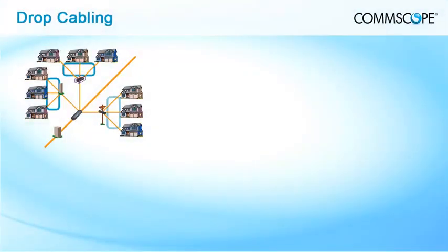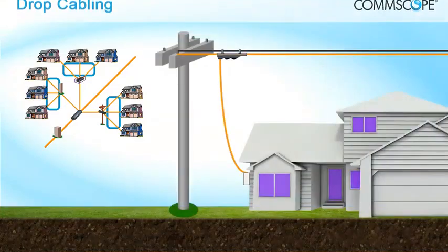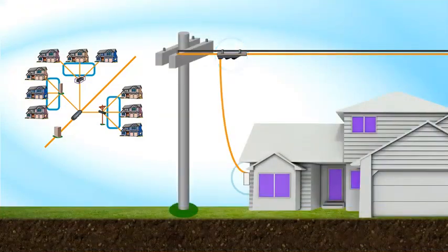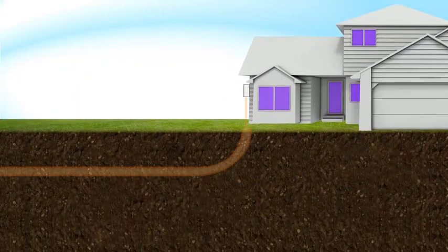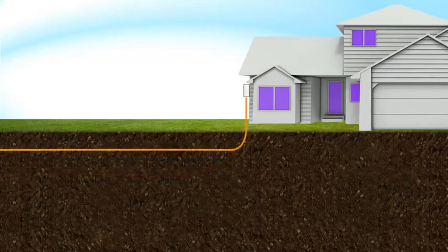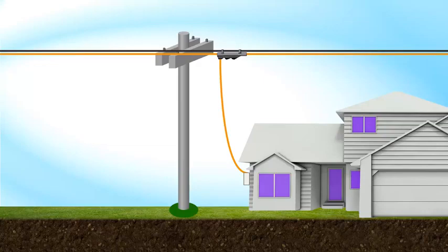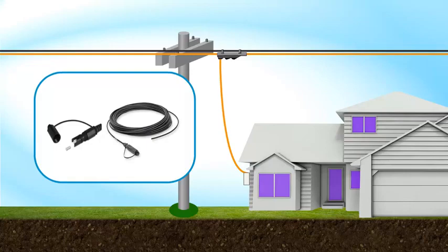Drop cabling forms the final external link to the subscriber and runs from the last FAT closure to the subscriber building. These drop cables usually have low-count fiber cores, but may include additional cores for backup or other reasons. For underground networks, the drop cabling could be via ducts or direct burial to achieve a single dig and install solution. Overhead drop cables will feed from a nearby pole and terminate at a chosen point on the building for onward routing to the termination unit.